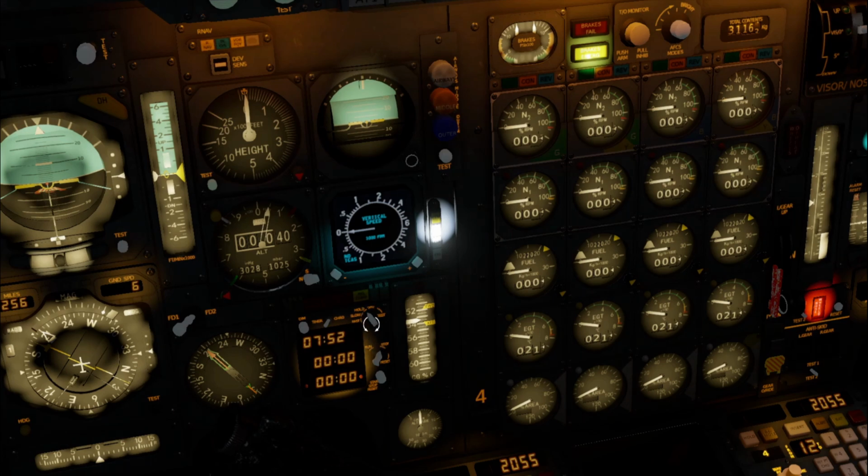There are a couple of charts for it for Concorde, but for Brisbane I don't have data, so we will estimate it only. So I will reset it and I will make, let's say, 40 seconds will be okay. I think we are very light, we don't need to have a long noise abatement procedure, and we will go full power for a short time.